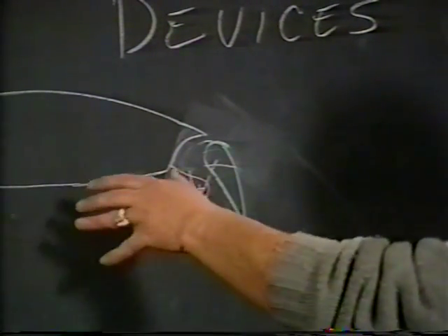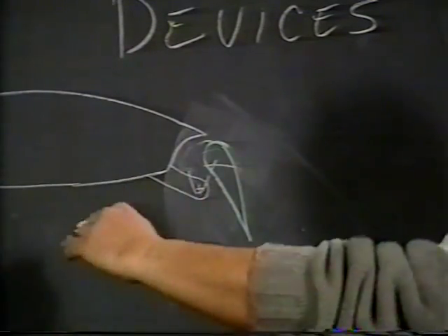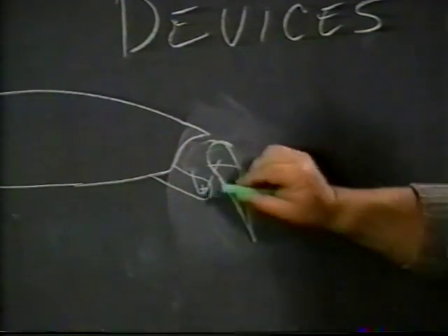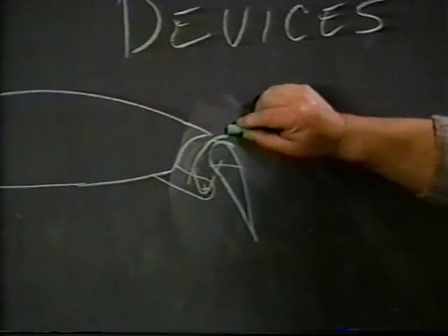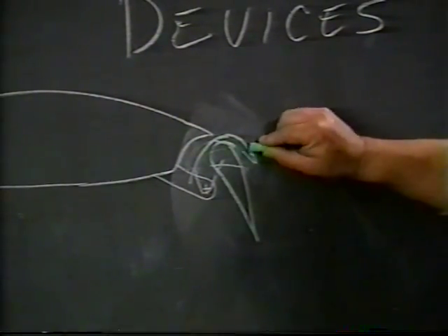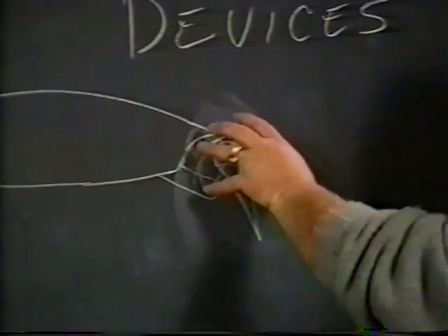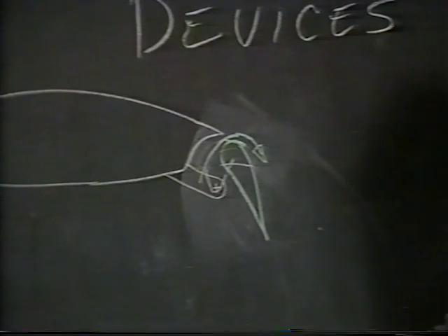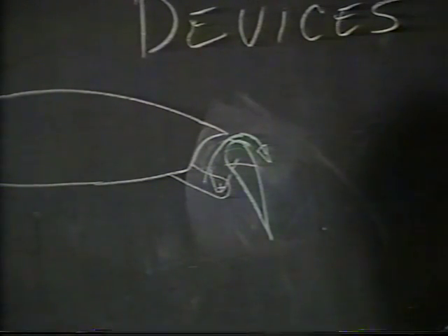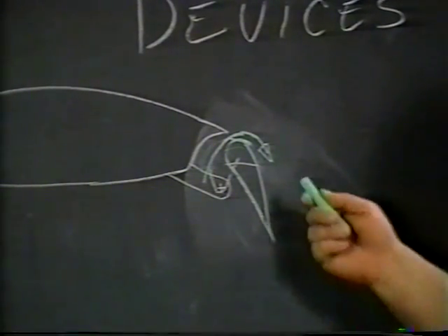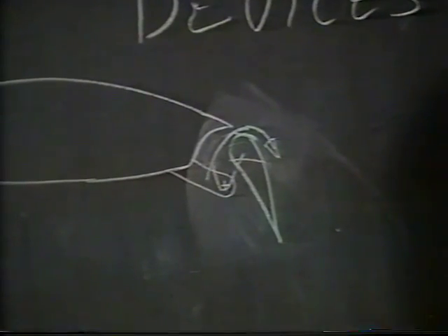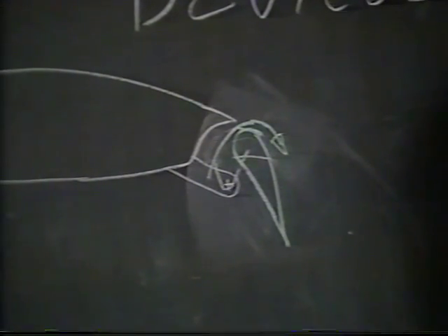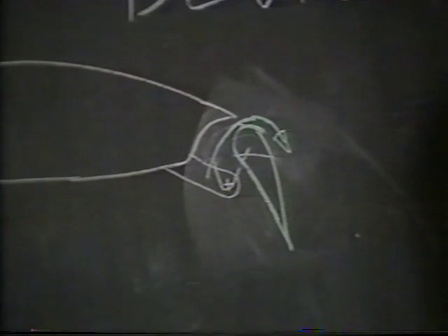But what it really does is when you're flying at a high angle of attack, the bottom air here is under high pressure. It comes around through the slot and really becomes almost a boundary layer control device on the flap section itself and produces considerably higher lift than the normal split or plain flap would do. The slotted flap here is a very common flap, a very good flap, a very effective flap.